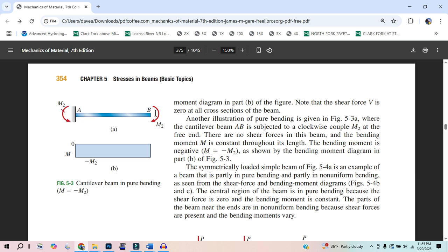So this diagram, as long as you can mentally just remove this connection, is a free body diagram. You know what I mean? This beam is just floating in outer space. I'm applying this load, and I must have to apply this load, which is an indication of an internal force, but it's the internal force right at the very edge of this beam.